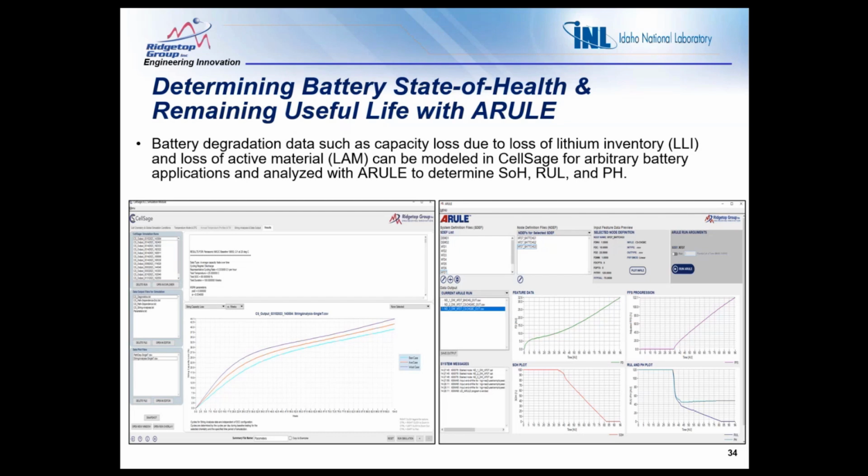And here with our collection of battery modeling and simulation tools, we found a growing application and use case for looking at different types of feature data from a BMS system, or even hardware-in-the-loop types of simulations where you can look at capacity fade or internal rise of resistance or other BMS data streams and variations from those data streams, and process that with ARULE to determine SOH and RUL in a closed loop environment. So it's very useful for looking at that and also investigating state of health estimation methods.